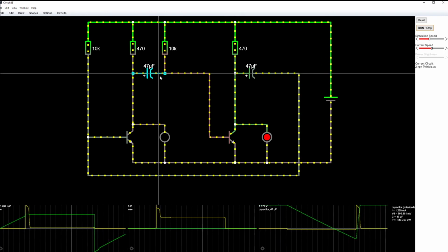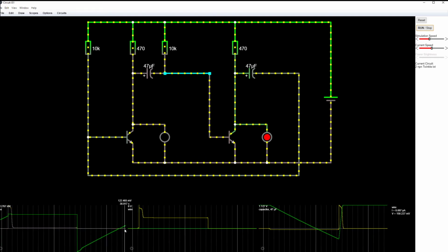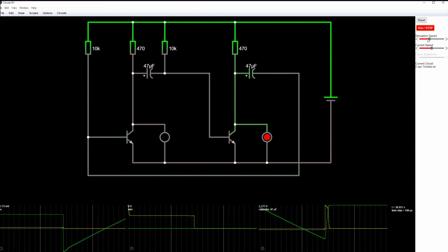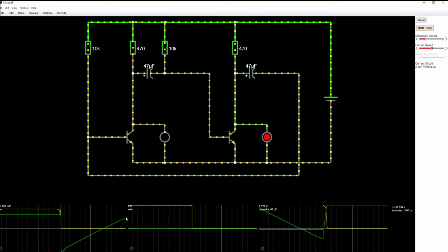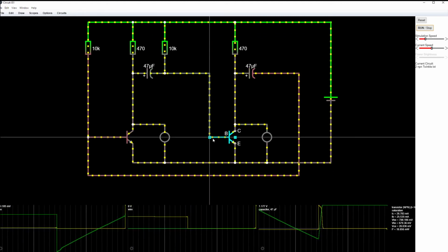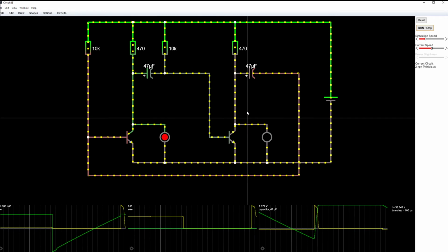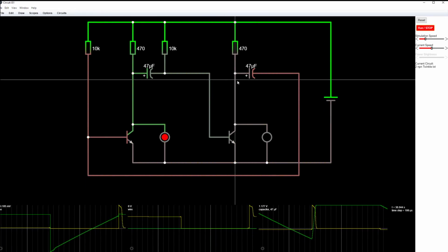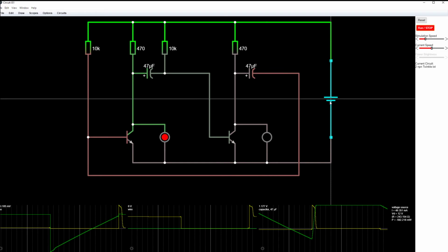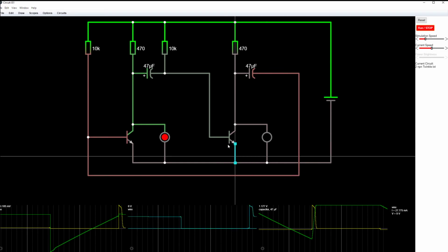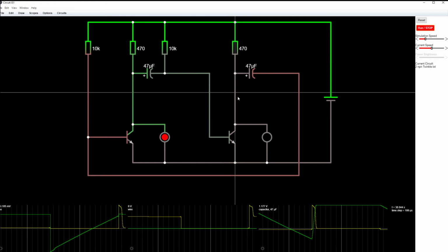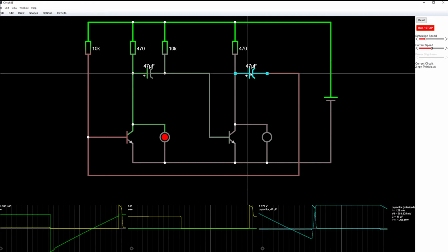And then over here, this line is slowly getting up to, let's go real slow now, once this gets up to 0.6, right, now it's opened this, and as soon as it opens this, this goes down to approximately 0 because it's connected to the negative part, the 0 from the power supply. So if you look at this graph, it was at 1.1 volts and then slowly it's draining down.